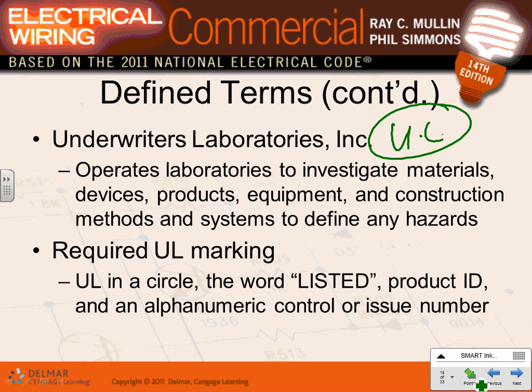You say, this is a 4,000 amp switchgear. You handle 4,000 continuously. Yep, let's put 4,000 in that sucker and see what's going to happen for 3 hours. If it stands, you get a UL listing on it. If it doesn't stand, it fails, send it back to the manufacturer. You can't put a UL listing on it. Does that make sense? It's a third-party verification.